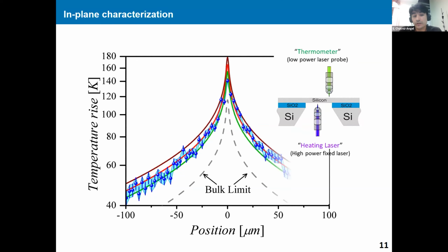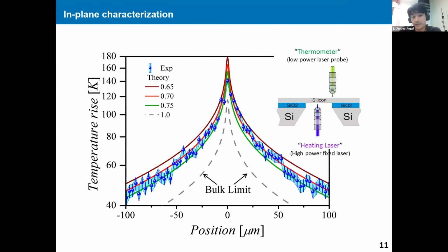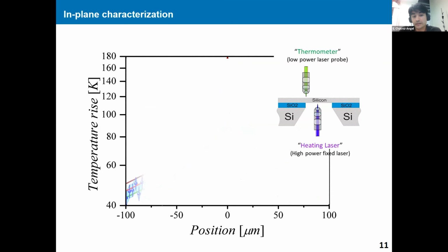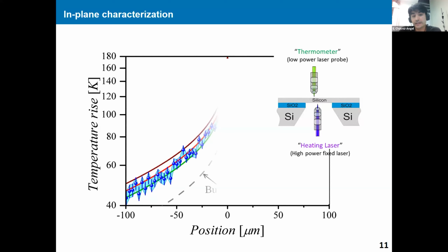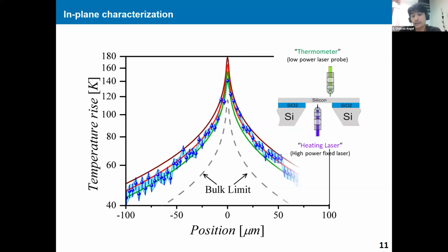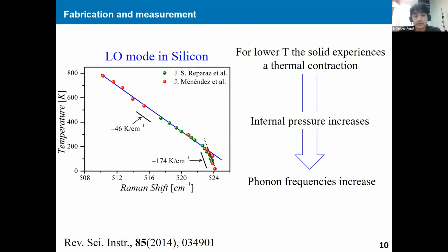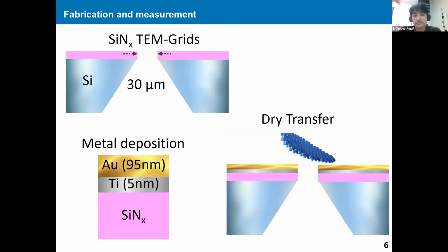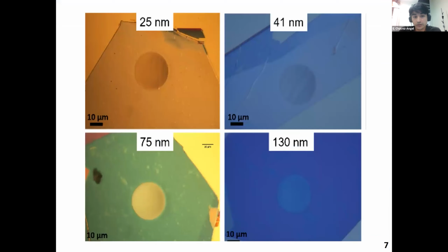And later, with a model, either COMSOL, or also there is an analytical way, we can extract the thermal conductivity, the in-plane thermal properties. And with that, we ensure we are always in plane, because the heat sink that you saw in this slide is in the surrounding of the system. We also create this hole circular in order to facilitate the simulations.